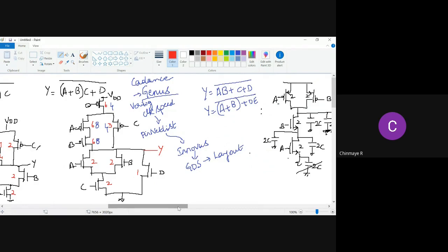Why are we doing an effective resistance of R, and why are we not meddling with the capacitors much here? It is mainly because the capacitance at the output that dominates the delay is the load capacitance, which is much higher than the parasitic capacitance. So therefore, we are trying to make the effective resistances equal so that this R and C, charge and discharge, are equal.